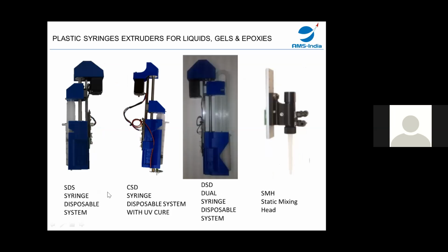So when you want to print, for example, Vaseline, or you want to print with resins, araldite, or quick fix, any such material, you can take this one because it is one time use. You fill it up in a plastic syringe, you use it and then throw the syringe itself. You don't need to reuse it again. Whereas your aluminum ones are not disposable like this, so you use easily cleanable materials there. Here, materials which are not cleanable, which are gluing and very adhesive in nature, are difficult for maintenance. So you use plastics here, you use and throw it.